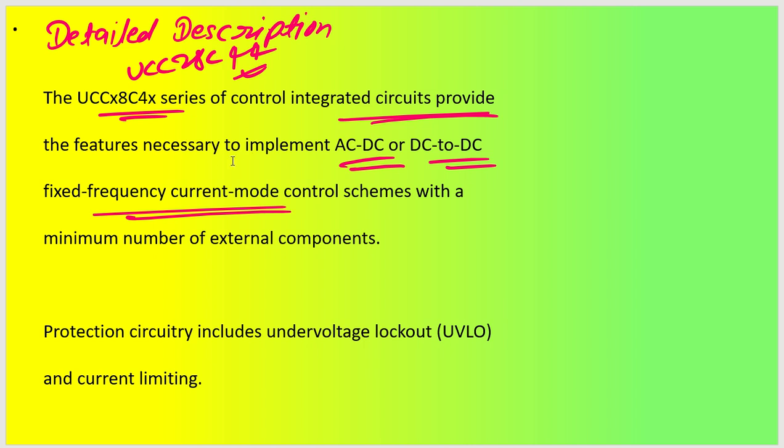Basically, it is going to give you all the features that are required for your AC/DC converter or DC/DC converter for fixed frequency control mode schemes. There will be a fixed switching frequency as well as current control mode, with a minimum number of external components. You will require very few external components, so you will not need a very complex design or have a very high cost included in your design. You have protection circuits including under voltage lockout as well as current limiting, so it won't fail in that case.